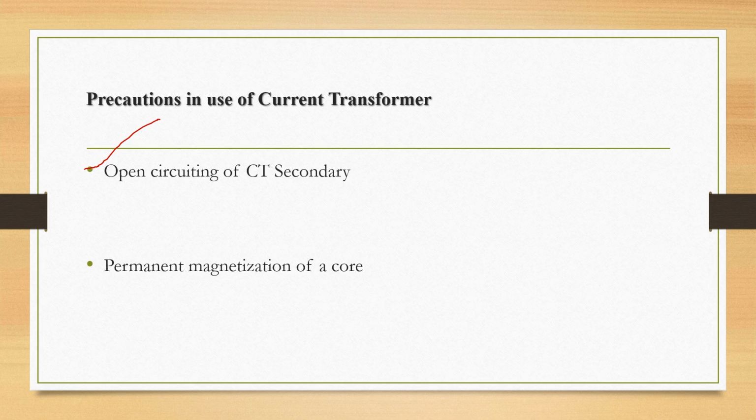Under normal operating conditions, the secondary current produces a so-called back EMF that almost balances the primary winding ampere turns and restricts the flux in the core. This small EMF is responsible for producing flux in the core and supplies the iron losses. This resultant flux being small, the voltage induced in the secondary winding is also low.